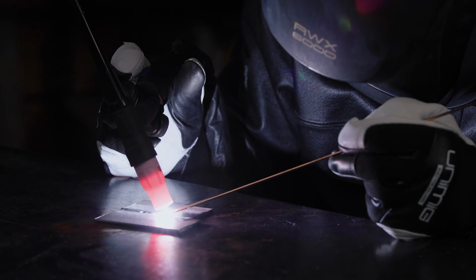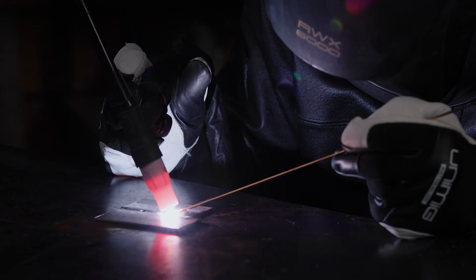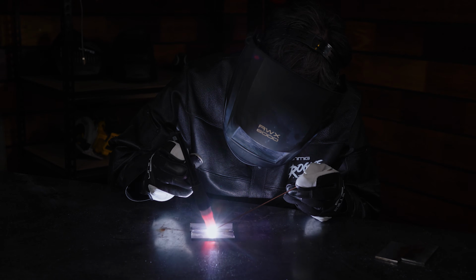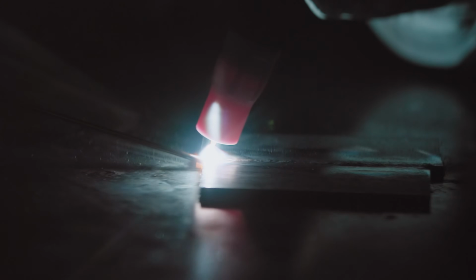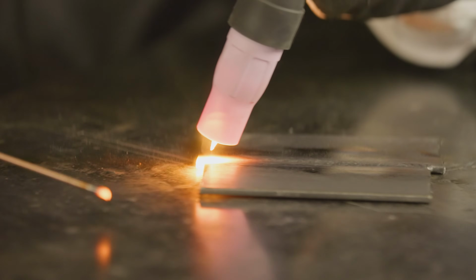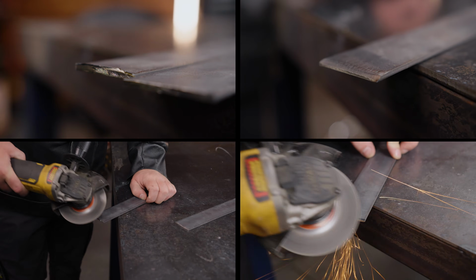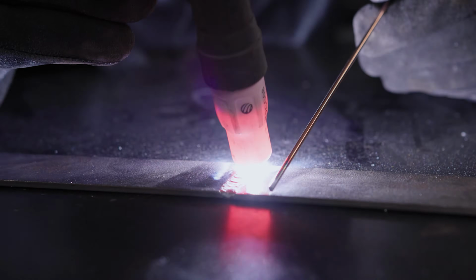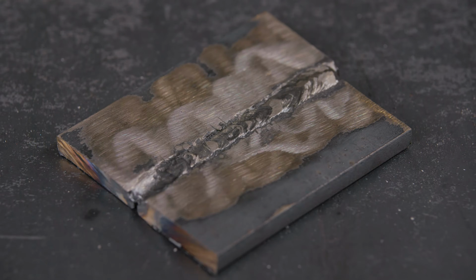How can you prevent or fix it? Use the correct type of gas for your metal type. For TIG, cool your metal slowly using an appropriate amount of post-gas flow for your weld. Preheat and post-heat your metal so that the temperature range isn't so severe. Make sure your filler metal, tensile strength and metal grade matches or is as close as possible to your parent metal. Use a backfill method to add extra filler at the end of your weld and let the weld build up slightly to prevent craters. Clean, grind, deburr, bevel and clamp your joint so that it's lined up as tight as possible with no impurities. If a crack has formed on your weld, you'll have to grind the whole thing off and restart.